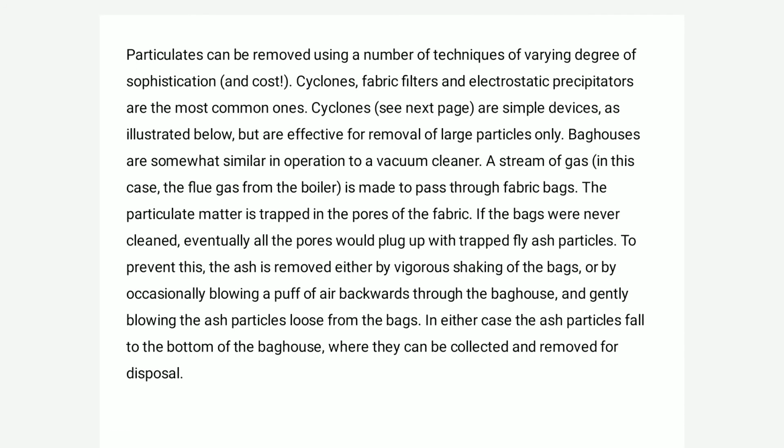Particulates can be removed by a number of techniques of varying degree of sophistication and cost. Cyclones, fabric filters, and electrostatic precipitators are the most common ones. Cyclones are simple devices, as illustrated below, but are effective for removal of large particles only. Baghouses are somewhat similar in operation to the vacuum cleaner. A stream of gas is made to pass through the fabric bags.